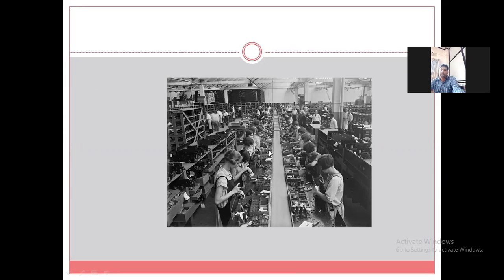Now what you require in the line balancing concept is that you have to understand the time required for each workstation. A similar kind of task should be provided, in the sense of time, to each workstation. Here what I am saying is that you need to calculate how much time it takes to complete a task at a workstation. So you will have to calculate the time of each workstation.